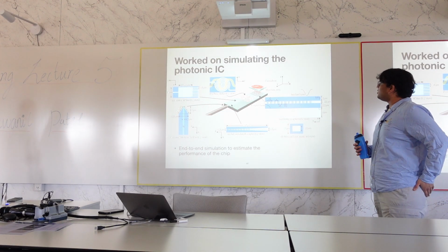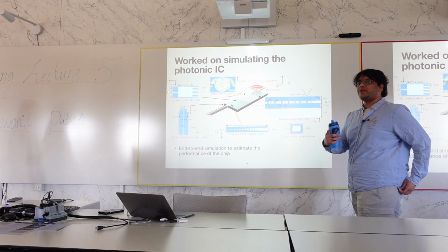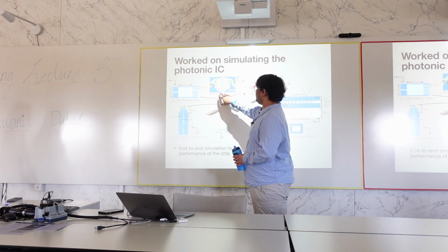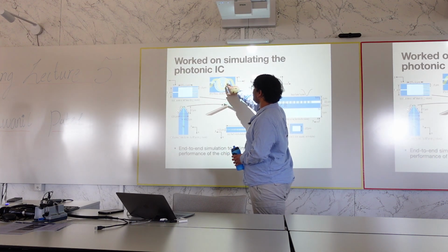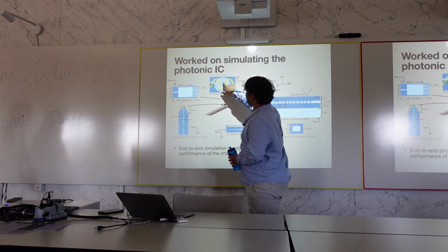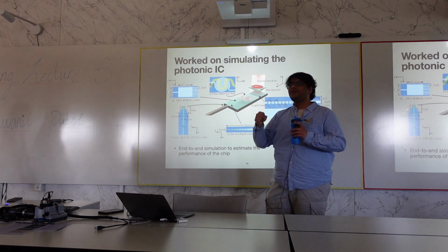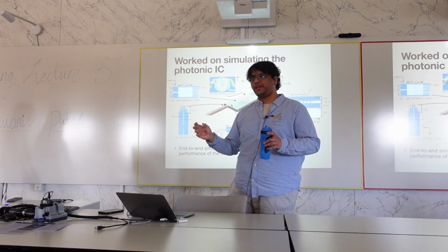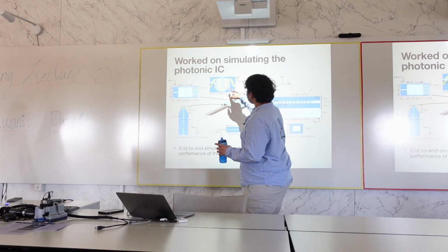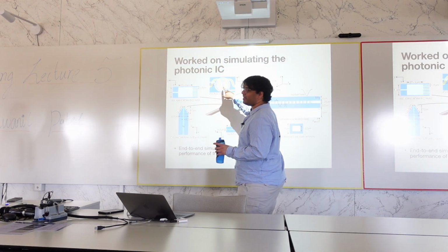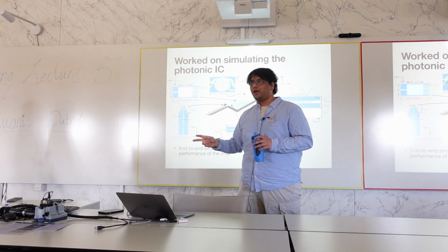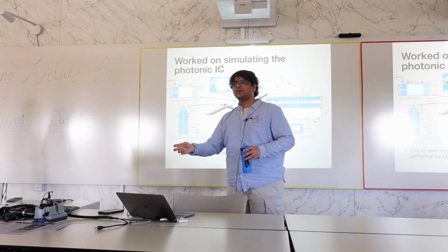Yeah. So the phase part you're talking about, you can change the phase of your light. Essentially, this is a phase shifter where you have a metal heater which acts on the light going through waveguides. When you heat these waveguides, the refractive index changes, and that's how we can change the phase of your light. Changing the refractive index means your light has to travel through a different material, so it adds an extra bit of path for your light.